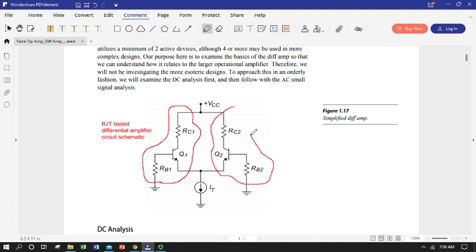It would work the same, a little bit different biasing, but these two halves of the circuit are identical, and it's very, very important to get the performance we want from the circuit that these be identical. So the collector resistors, the transistors, especially their betas and their beta temperature responses, and our base resistors, and as we'll see, the AC base emitter resistors are all going to be the same.